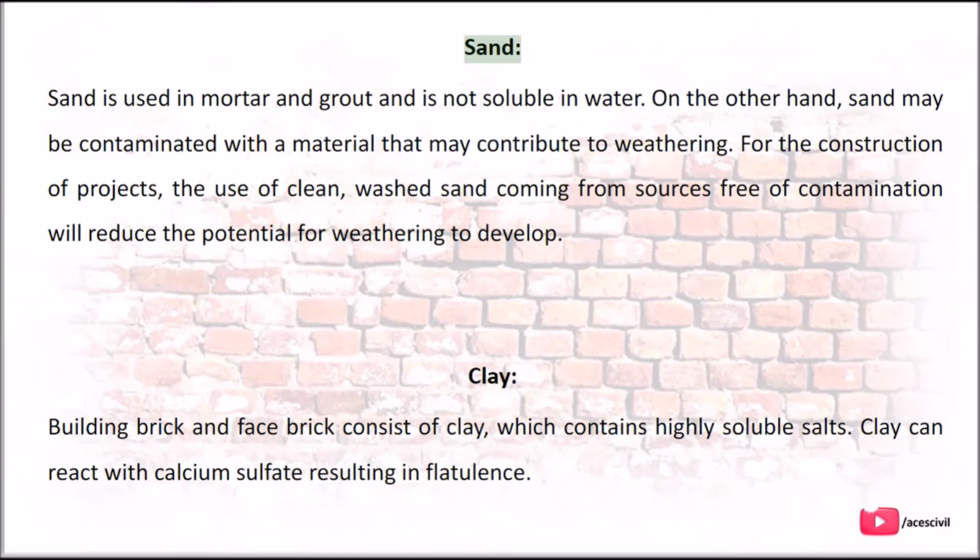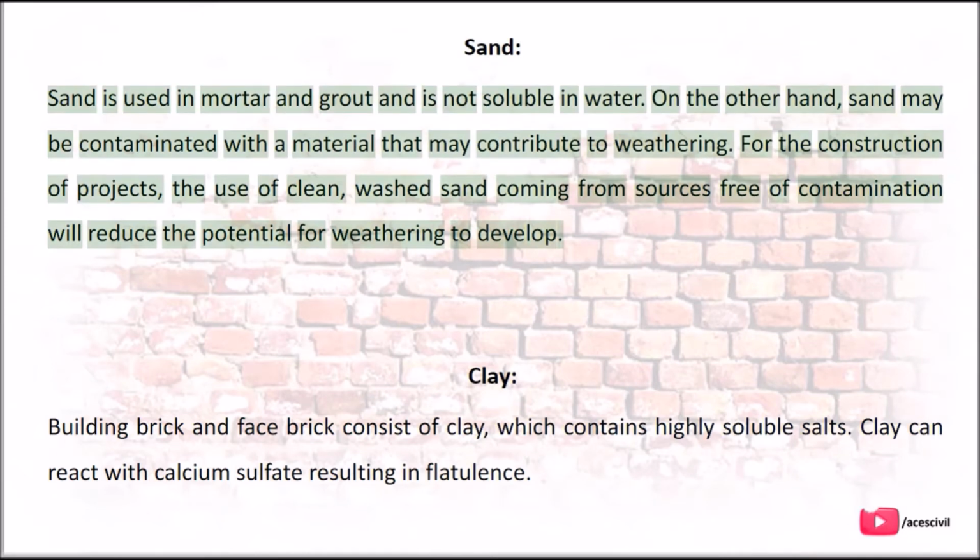Sand. Sand is used in mortar and grout and is not soluble in water. On the other hand, sand may be contaminated with a material that may contribute to efflorescence. For the construction of projects, the use of clean, washed sand coming from sources free of contamination will reduce the potential for efflorescence to develop.